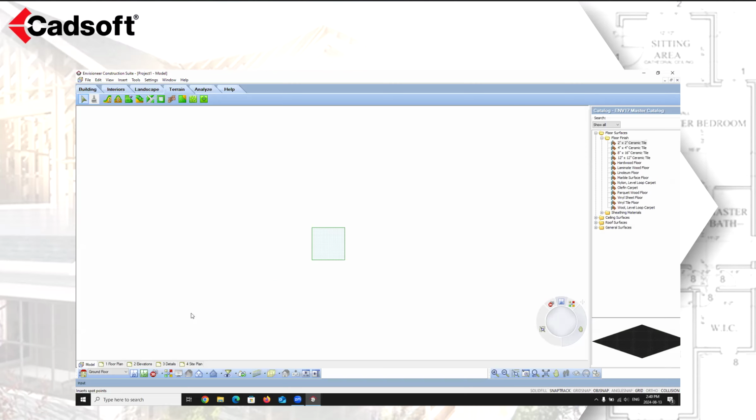What this will do is revert it back to the default terrain, which will allow you to add in your hills and valleys and slopes and plateaus and all of that fun stuff with the terrain editing tools. But I'm resetting the terrain because I want to show you the last option here, which is your spot points. This is the option that I use most often. So if I don't get site information from my surveyor, but I want to show the topography of the site, I'm going to use the actual spot points.